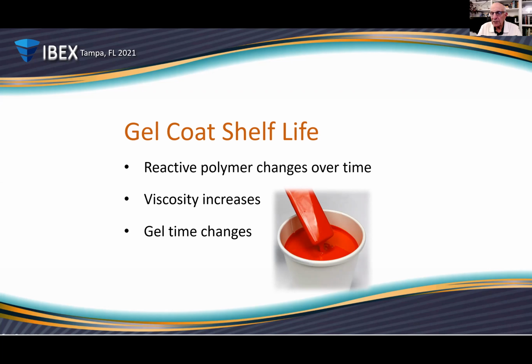Now, one of the other things that's involved with shelf life is storage temperature. If you're storing material in elevated temperatures as compared to cold temperatures, it makes a difference. So if your gel coat is stored in an outside lean-to in Florida during the summer, it's going to be way hotter than somebody who has their material stored in a lean-to in Minnesota. The stuff in Minnesota is going to last longer within specification because the temperatures are not as high.